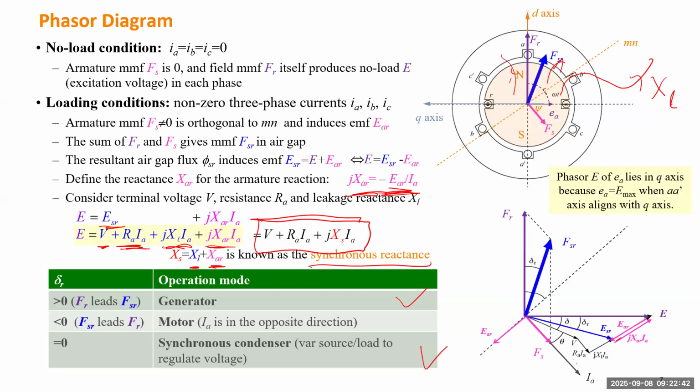Remember from the previous session, we developed the formula to calculate the real power over a transmission line. The angle difference tells how much real power you deliver. So if the angle difference is 0, so if this V and this E are in the same direction, there's no real power. We just call it delta, indicating their angle difference.